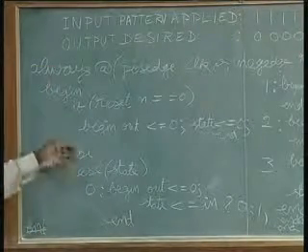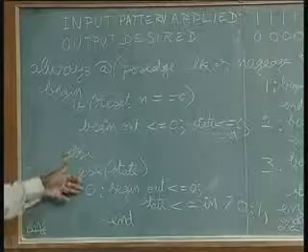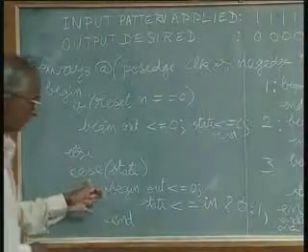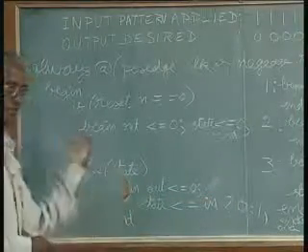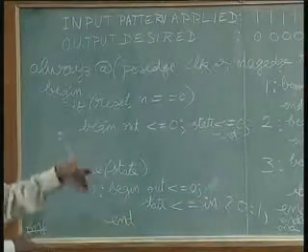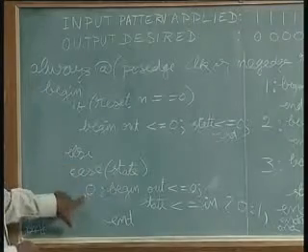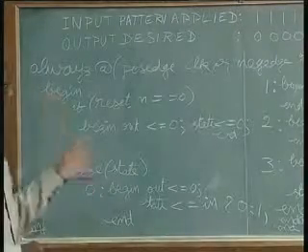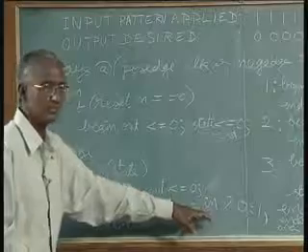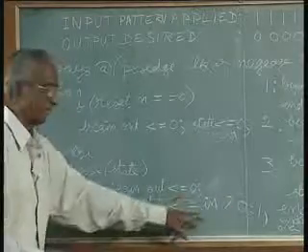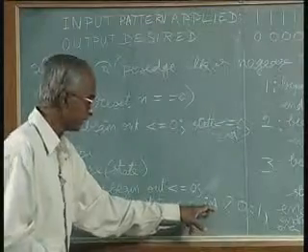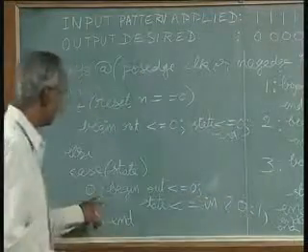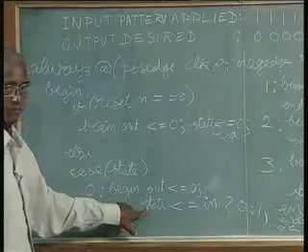So it continues to be in 0 state. Let us say at some nth clock it has entered this for the first time, and it says state will once again be put to 0. With the arrival of the next clock pulse, it will again come to the same state, and it continues to be in the same state so long as in is 1. Suppose in is 0. Then what happens? State will get updated to 1 now.